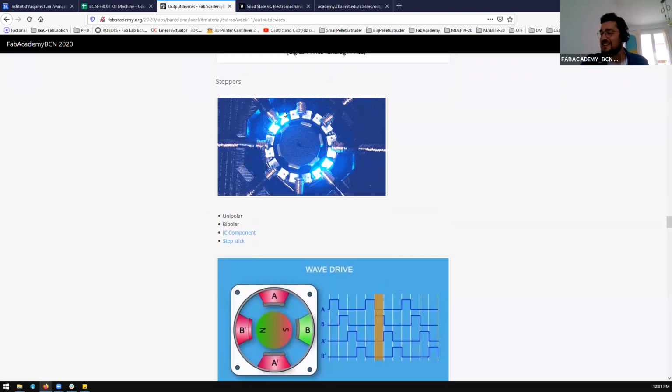So actually, as he was stating, it is 4 states, and those are called the poles. More poles means you can make smaller steps, and you can control with smaller angles of movement. But by doing so, you are also decreasing the size of the magnets and the size of the poles. That means each pole has less attracting power.